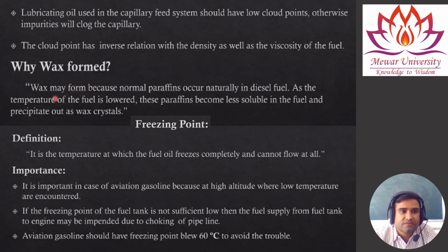Wax may form because normal paraffin occurs in diesel fuel. As the temperature of the fuel is lowered, these paraffins become less soluble in the fuel and precipitate out as wax crystals. So this is because of the presence of paraffin.